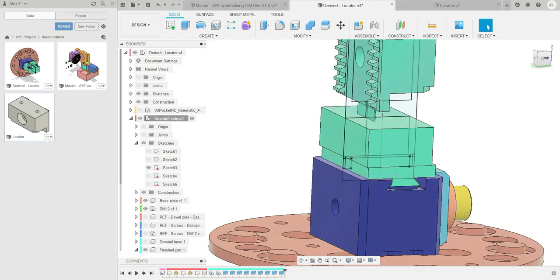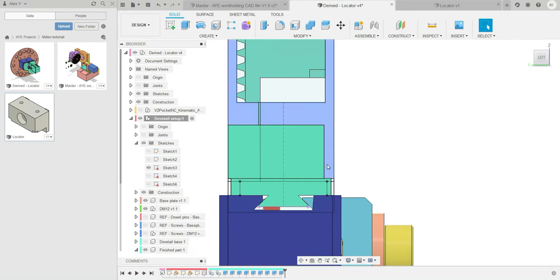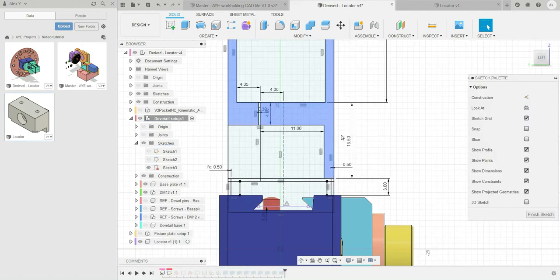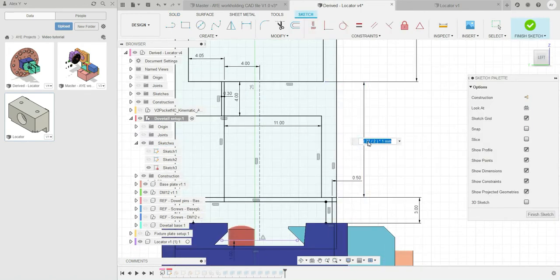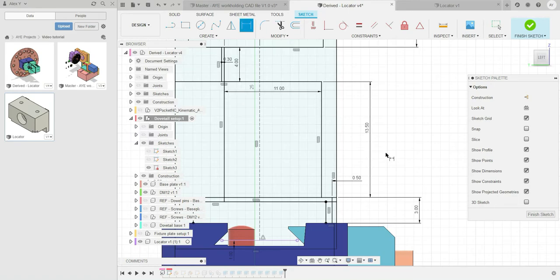And I've also just realized that I set the spindle clearance to this point here, whereas I've got the tab in now, so I need to set the clearance to this point rather than up there. So I'll go back into sketch 3, edit. So yeah, there's 13.5, which is the spindle width divided by 2. So I need to set that as being that height now. So I'm going to just escape out of there. I'll just copy that, then escape. Now delete it. Press D on my keyboard to bring up dimension. Select and then paste. Enter. There you go.